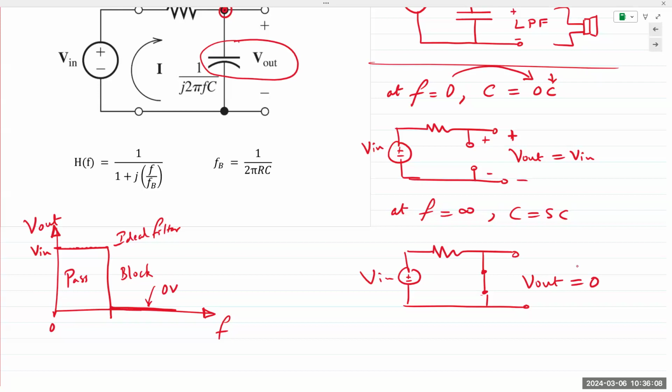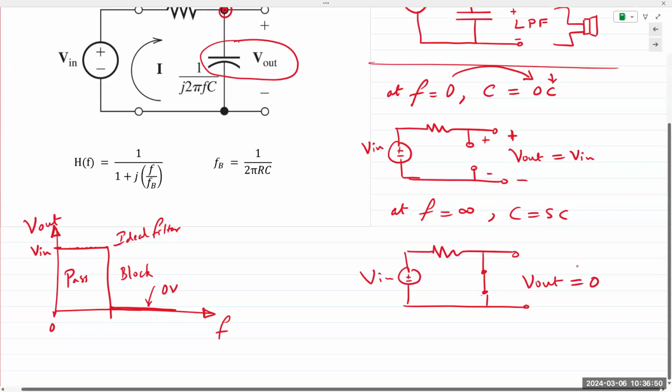And so low or high frequencies is basically relative. 16 kilohertz or 20 kilohertz for human hearing would be considered very high frequencies. But if you think about your wireless routers or satellite signals, mobile communications, they are in the megahertz and the gigahertz range. A wireless router works in the 2.4 and the 5 gigahertz band. So for a 5 gigahertz band, kilohertz is nothing. Kilohertz is a low frequency, whereas for human hearing, it is considered to be high frequency. So low and high is relative. It depends on the application. Does that make sense?